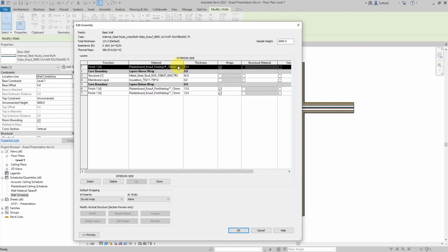The second thing we see is how the framing material is named. Although we won't see the cross-section of the studs in our plan views, we'll still know the specific stud arrangement needed to achieve our desired wall heights, since it's instantly documented in both the family parameters and the materials themselves. The third thing we see is that insulation is included as its own material and given a specific name. Again, the setup will help in the material takeoff later.